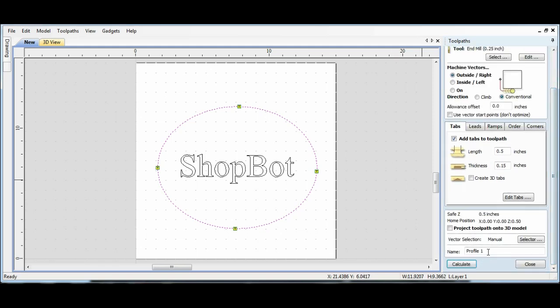So that's good. We got everything set up, and now we're ready to name that toolpath. You can name it whatever you want. I'm going to say sign outside profile. And I typically, especially if I have a lot of parts, I'll name exactly what it is, and then I'll just say full cutout. That way, if for whatever reason I forgot to screw something down, and I'm loading up this toolpath on the CNC machine, and I see full cutout, I'm like, oh wait, I don't have a screw there. That's going to pop out and screw stuff up. It's just another safety net for me.